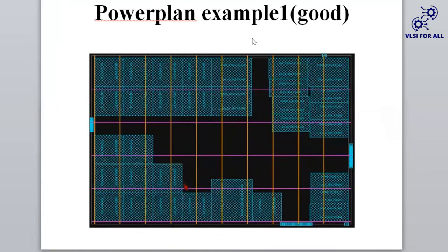These metal stripes are arranged such that if metal 1 is used horizontally and metal 2 vertically, in the horizontal-vertical HV methodology, the metal layers are placed alternately. If odd metals are used horizontally, then even metals are used vertically. In this methodology, metal wires are distributed in order to connect the macro pins and standard cells.